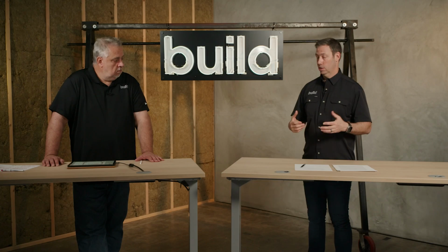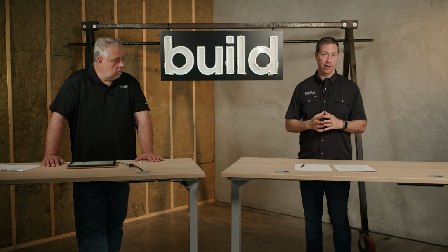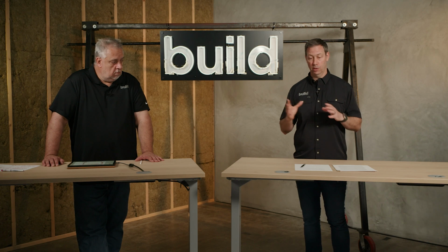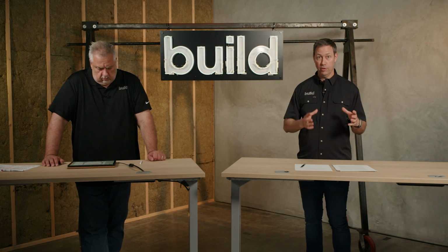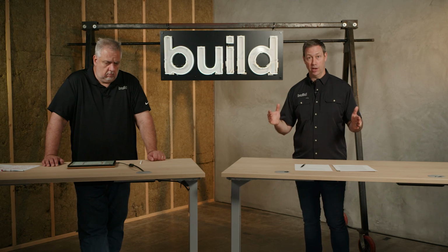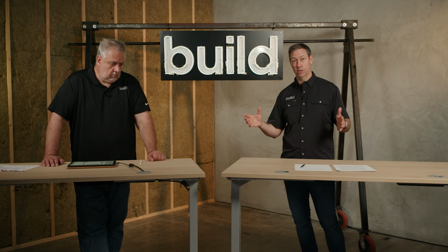A much looser standard. Where I am currently, as we're filming this, we need to make a 5 ACH 50. Let me just break it down real quick. We're at 3. So 5 air changes per hour, ACH, at 50 pascals of pressure differential between the inside and the outside.